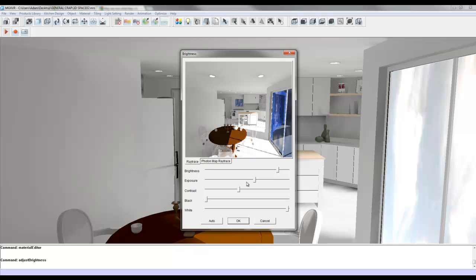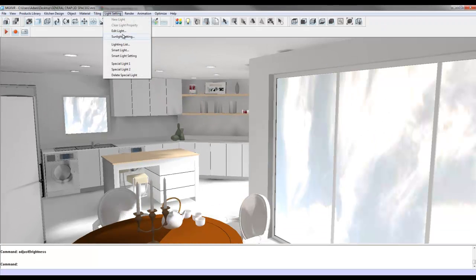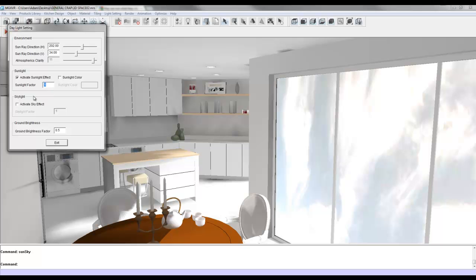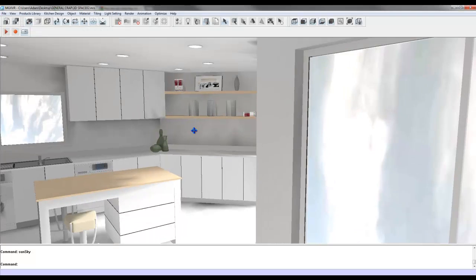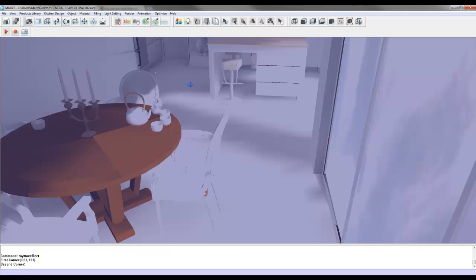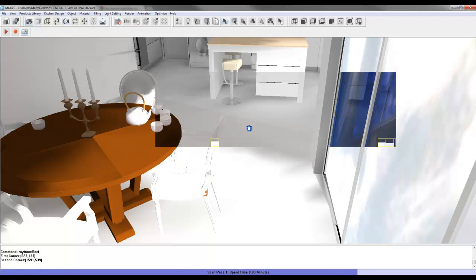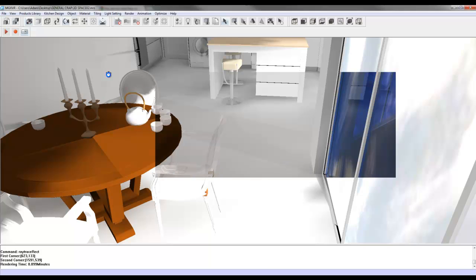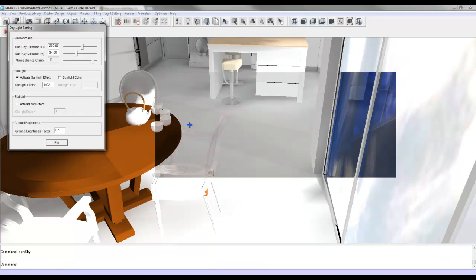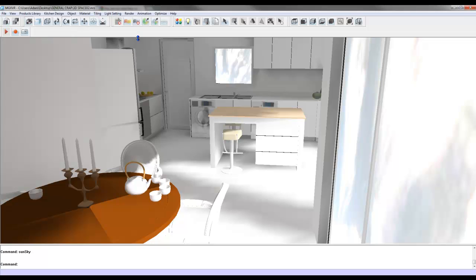And then on the rendering side, one thing I would do is drop the sunlight value down. So let's see what it's set at. It's 1. I'm going to make this 0.02. Okay, let's see if it's made a difference. I don't know if we have to re-render. No, actually 0.02 might be a bit low in this case, so let's push that up a bit. It's 0.3. That should be fine. And then carry on with the rest of the project.